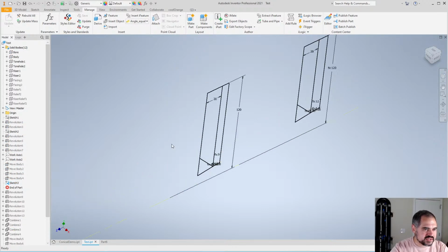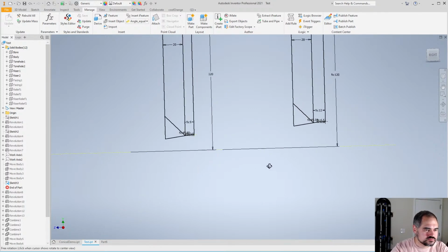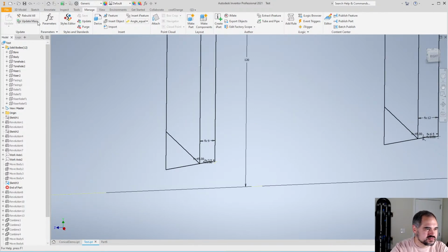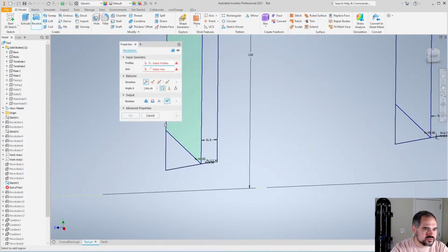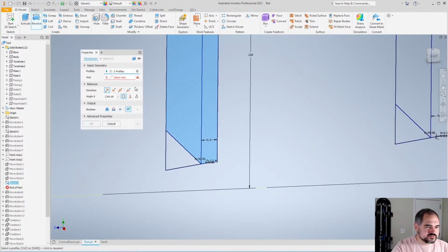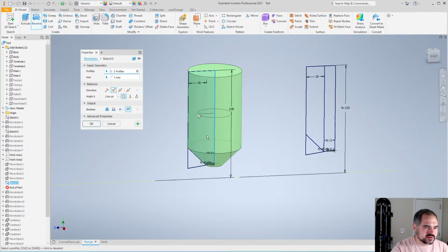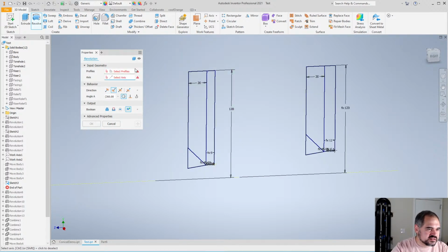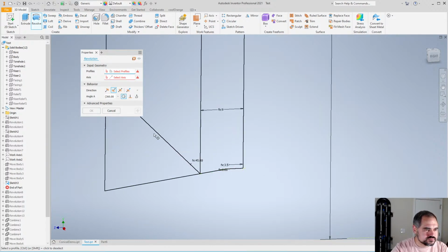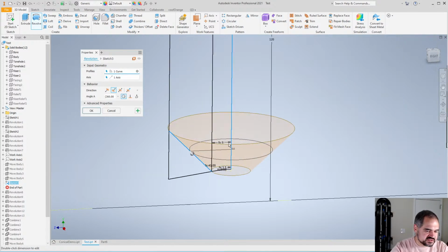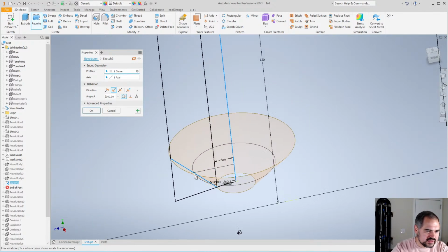If I go back to my tone hole relief and facing sketch, instead of what I did, which was rotating this into a solid, one option is if I click this button here, I can rotate it into a surface like that.